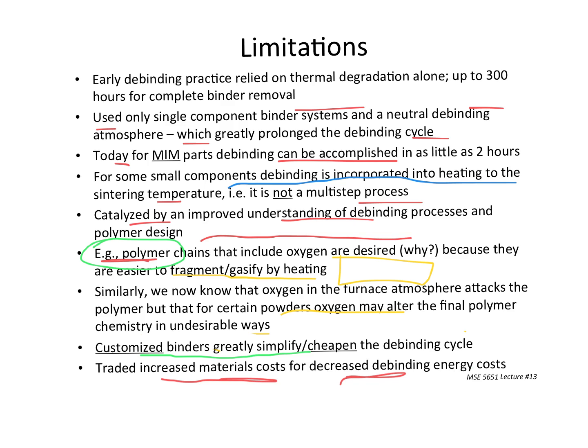It does expire. The other aspect of it, though, is that these are polymers and they're additives in the process. When this part finally comes out at the end of the furnace process, there's no evidence that polymer was ever there. So if I know someone unscrupulous enough, I can pay them to make this polymer structure, because now I know what it is, and sell it to me, and I can use it in my parts, and no one will ever know, because when I sell these injection molded femoral heads, there's no evidence that polymer was ever there. And so this is why we have trade secrets, because stuff like this can happen, and it's true for a lot of processes where an aid in the process is no longer there in the final parts.